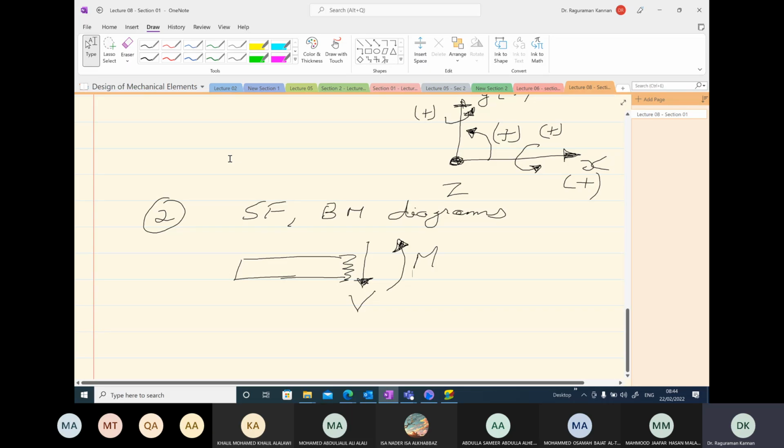If you make a cut on the left hand side of the beam, then too your shear force must lead to clockwise rotation of the beam, which means the shear force must be pointing up in this case. And the bending moment, on the other hand, should again make the beam into a shape that can hold some water.